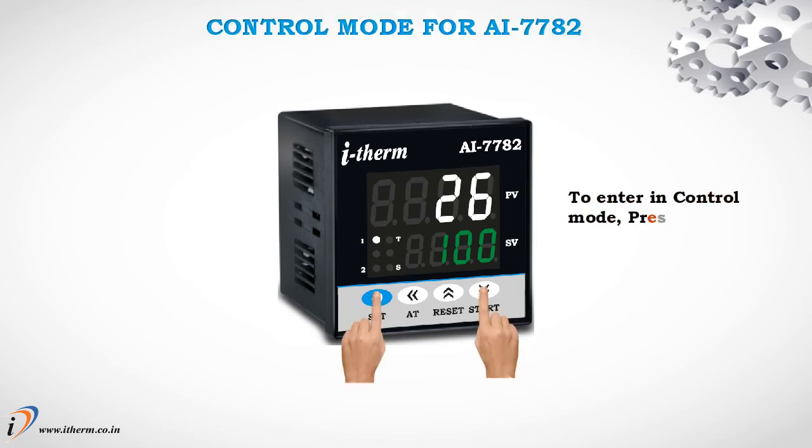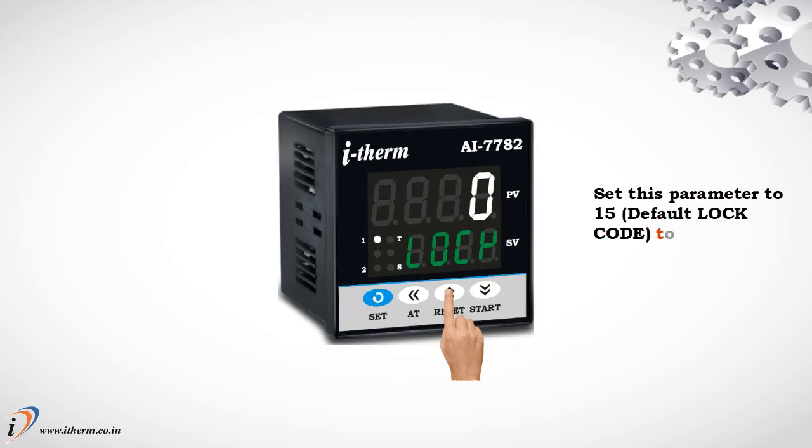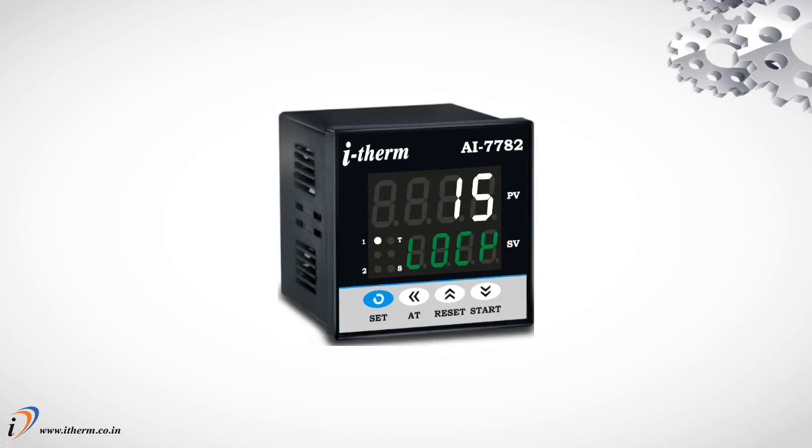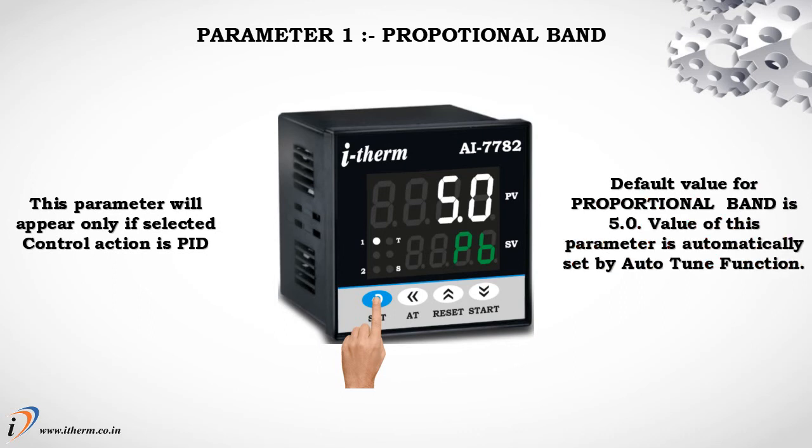Control mode for AI7782. To enter in control mode, press and hold the set and down key simultaneously for 3 seconds. Set this parameter to 15 to access the control list. Parameter 1, Proportional Band. This parameter will appear only if the selected control action is PID. The default value for proportional band is 5.0. The value of this parameter is automatically set by the auto-tune function.